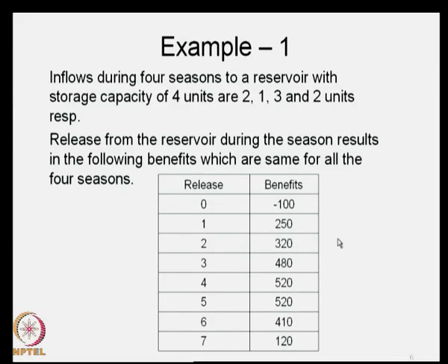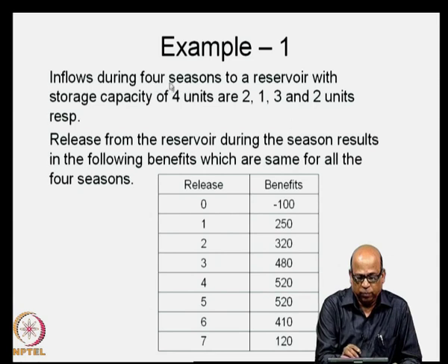Now, we will take the example. In fact, this is the same example, with the same data, that we introduced for dynamic programming in perhaps lecture number 16 or 17. I encourage you to go to those lectures and see this particular example. We are just picking up the example and then solving it for several years until we reach a steady state. So, the benefits are the same, there are 4 time periods, that we call 4 seasons, and the reservoir capacity is 4 units. You have the inflows 2, 1, 3 and 2 units,